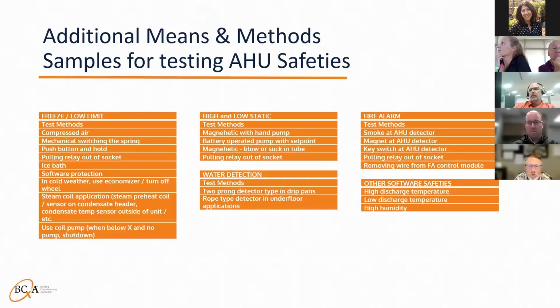This was in a conference room, open to adjacent spaces. The CO2 sensors that we've been using do have a foam seal to go onto the back of them. Most of the time you do not see an installing contractor sealing conduit or sealing that wall cavity, but they will put that foam backing seal between the actual device and the wall.